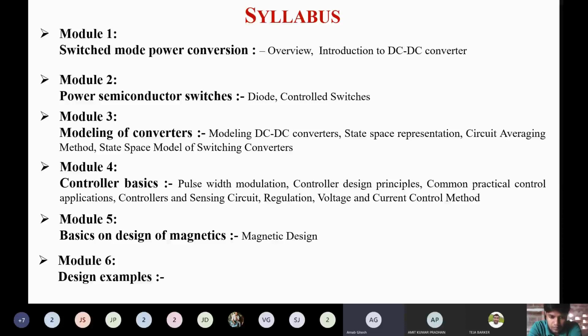Okay, so why are you going to compare that control signal to a triangular signal? Because you know that your switch normally needs a pulse. How do we get that pulse? Your control signal is more or less a fixed voltage, or a very slightly changing voltage.